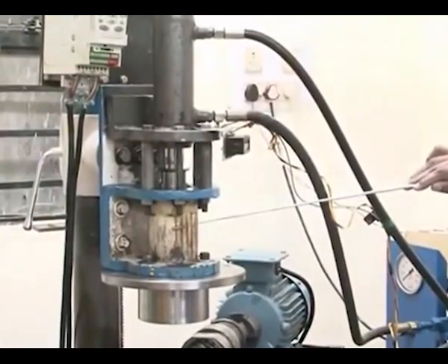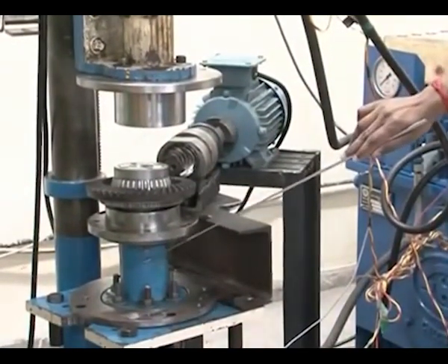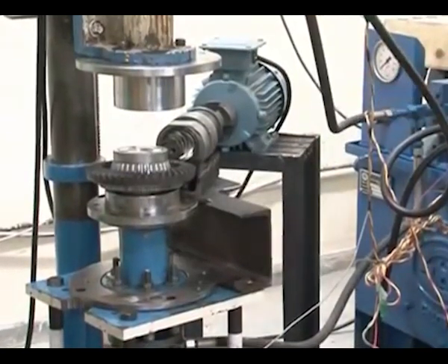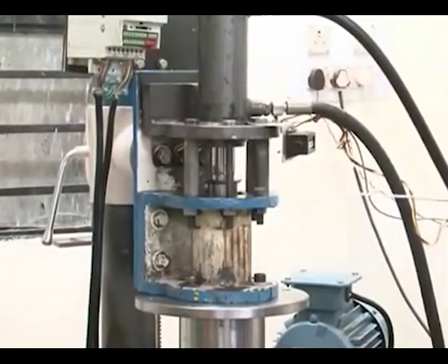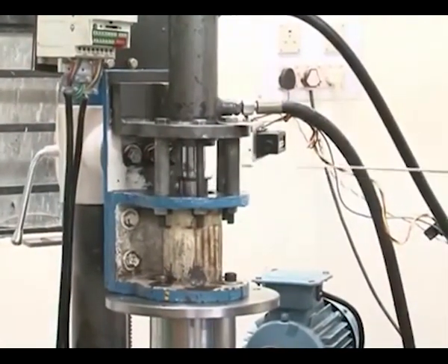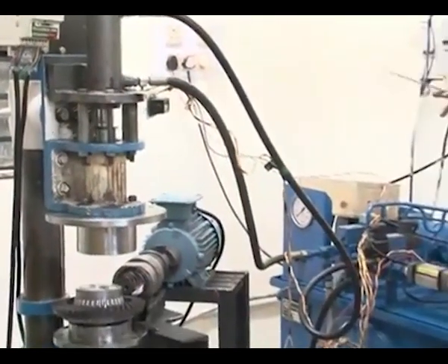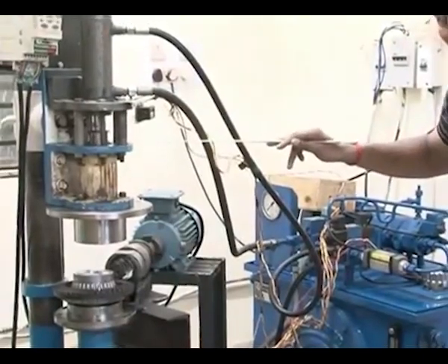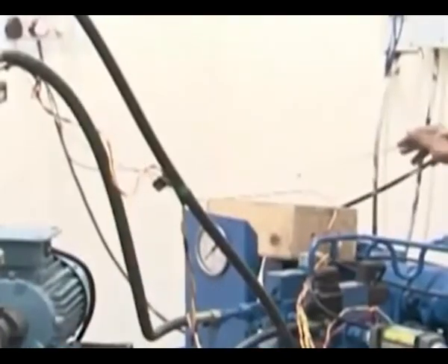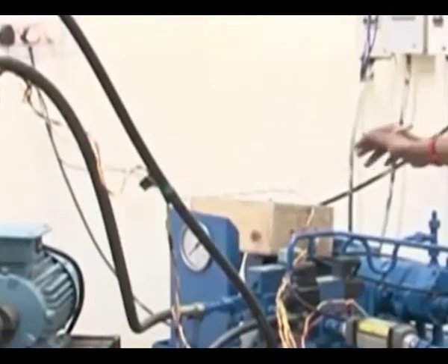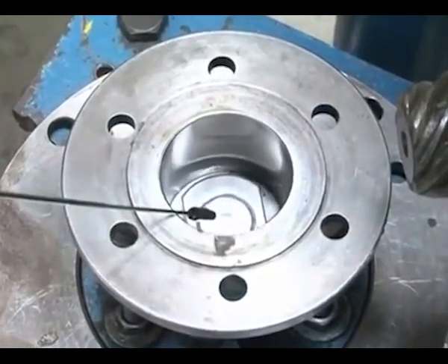This is upper medium cylinder and this is lower medium cylinder. We place the medium in the lower medium cylinder and we try to reciprocate. Now you will see how the machine will reciprocate. Now you can see the piston movement. This piston movement is given by the hydraulic power pack, and this bottom stroke and top stroke is controlled by an electronic controlling box. This is the electronic controlling box which controls the electronics of the limit switches. Now you can see the reciprocation motion of the piston.